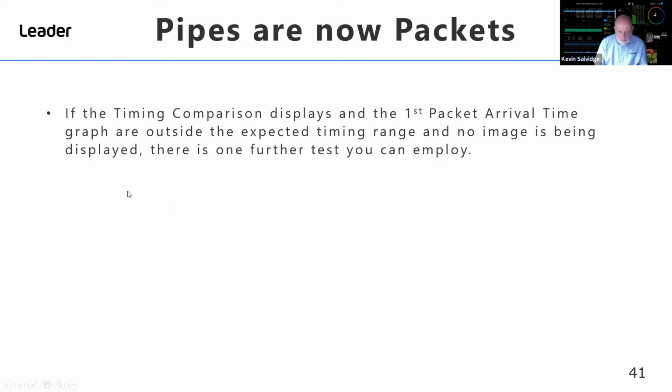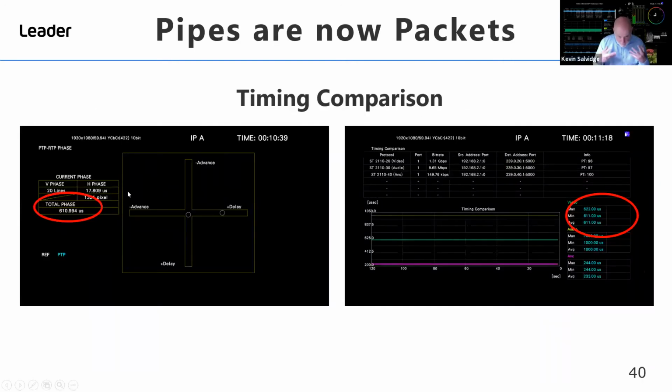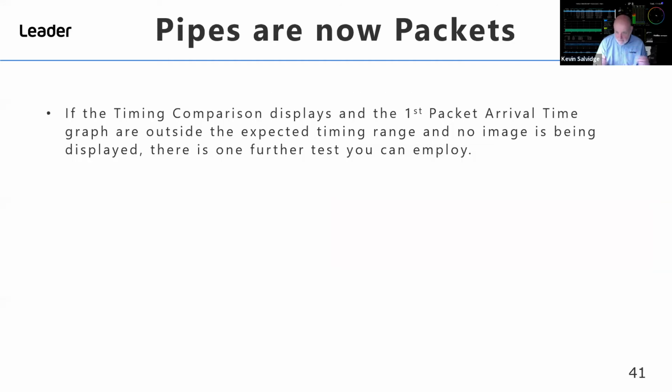So would it be fair to say, Steve, if you remember anything from this, if you're looking at timing, interlaced is 21 lines, progressive is 42 lines. Get those numbers, make sure they stick, because that's a great place to start looking to see if the active picture is in the right location.